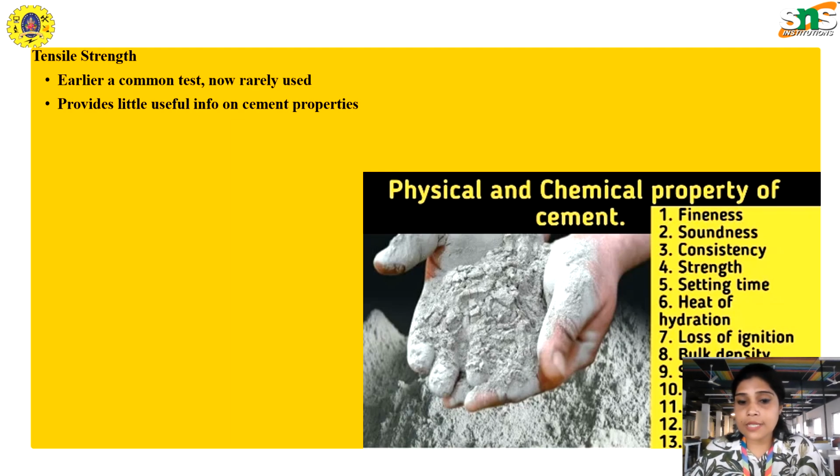Direct tension tests or indirect methods like splitting tensile strength and flexural tests are used to measure this property, with results depending on the testing method and the specific cement paste composition.